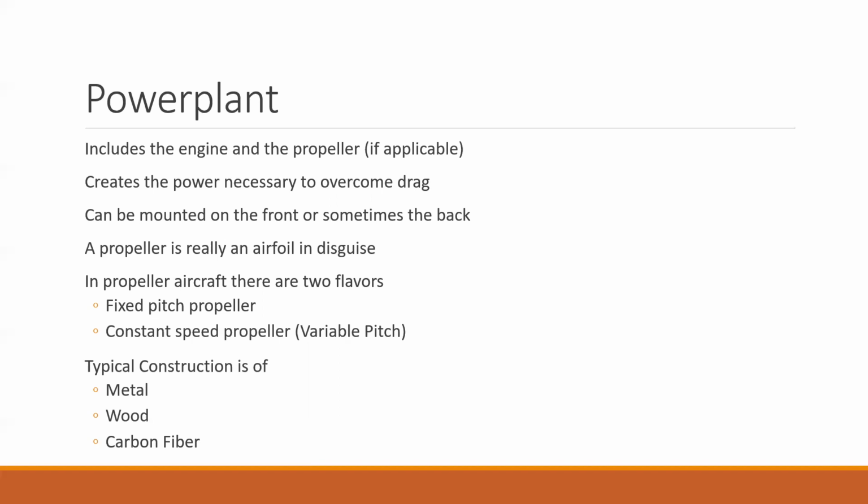And usually it's somewhere around your cruise speed. And that propeller is tuned so that it works very well at most airspeeds, but it works especially well at that cruise speed. And so you can't change the pitch of this. It's very easy to work. You don't have to worry about changing it based on your flight configuration. So that's nice. And a lot of very simple aircraft, Cessnas, have these type of propellers.